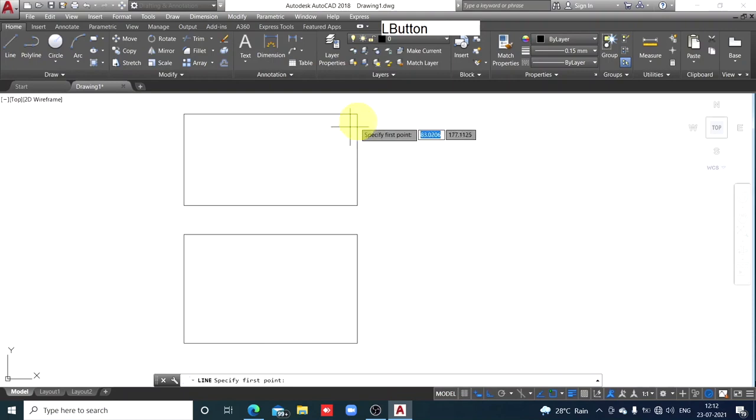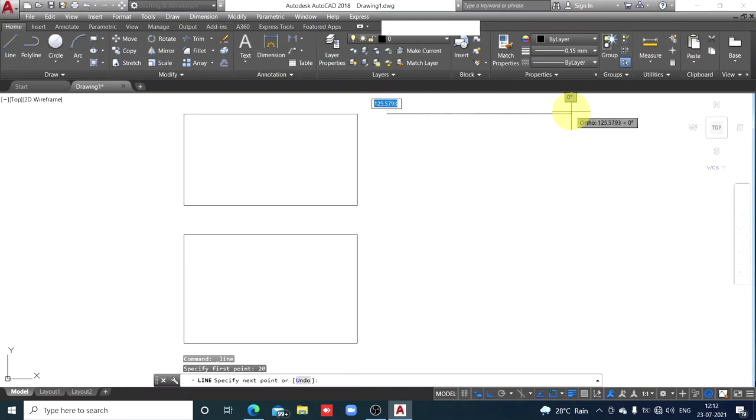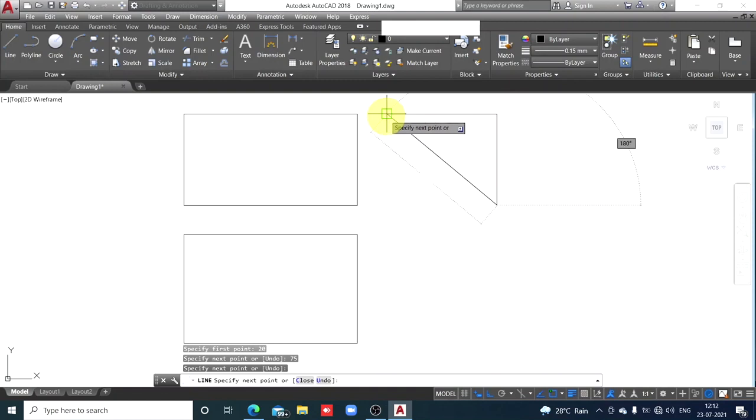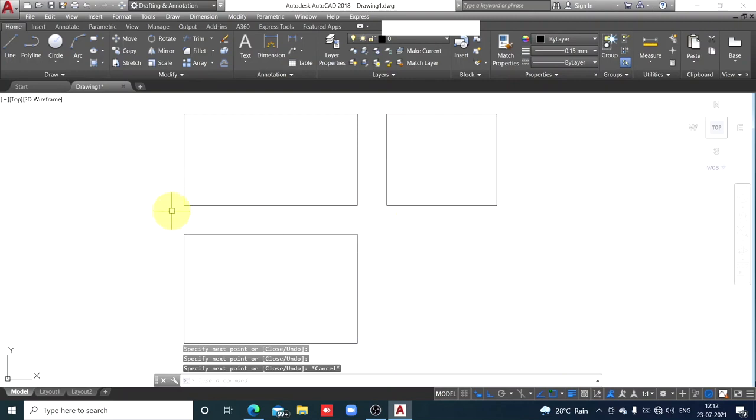Now click on the line, track the highest point, take the cursor to the right side, 20 millimeter, enter. So this is the start point of the line, and width horizontally in the side view, 75, enter. Then height, I'll track this point directly in this manner. Then I'll track the top point. So this is how I've completed the rectangles.